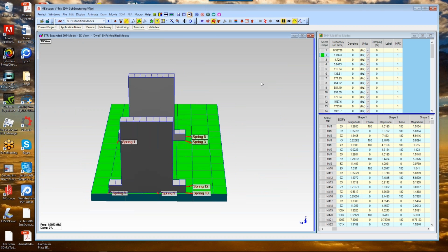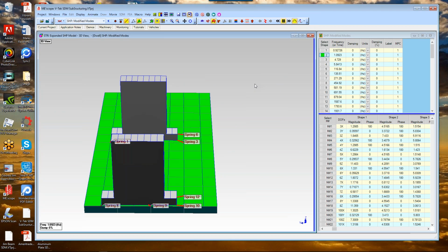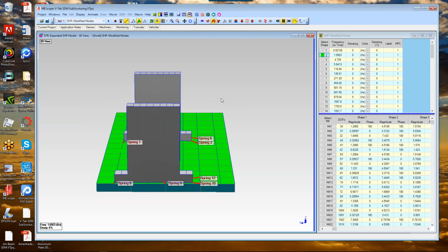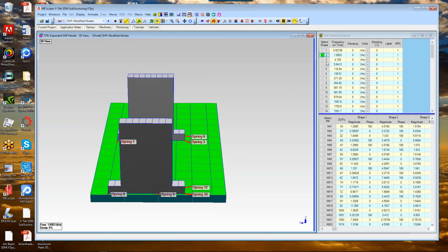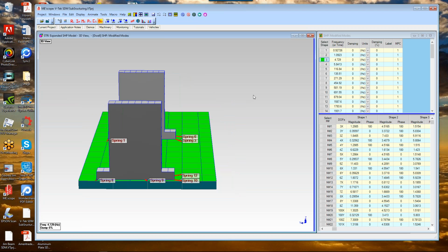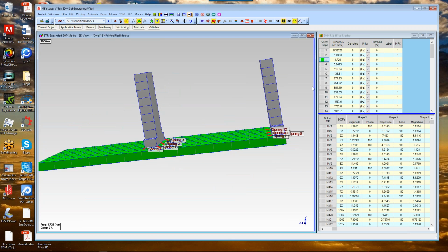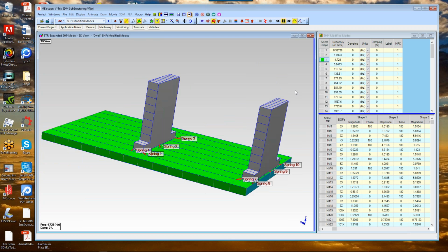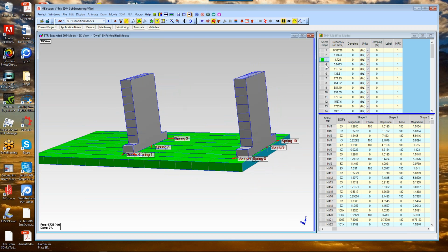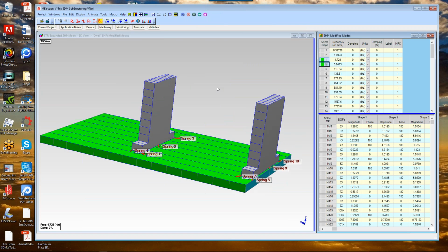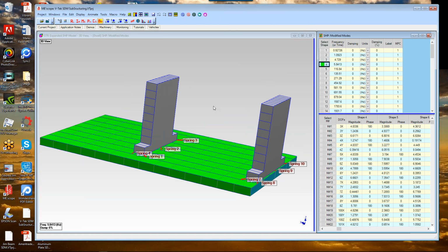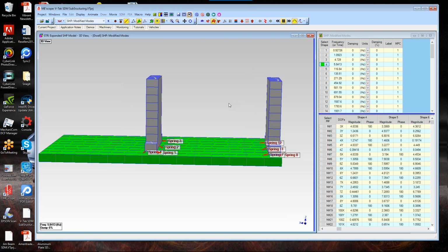The bearing blocks are actually mounted on one side of the structure. And as I rotate around, there's another rigid body mode. The blocks are just attached and rigidly moving as the base plate and the whole assembly rocks in space.